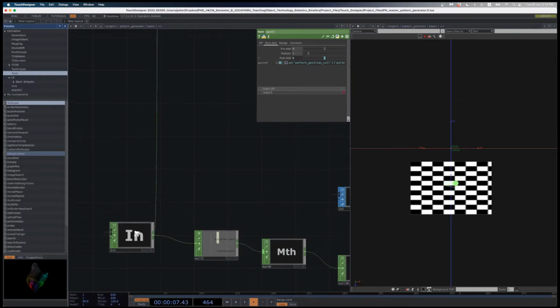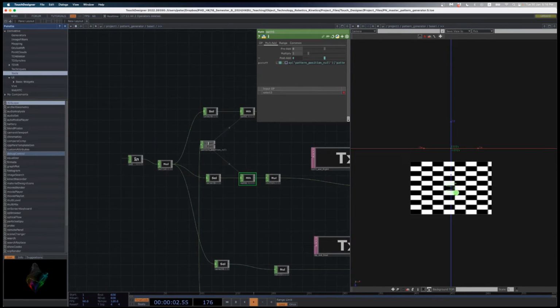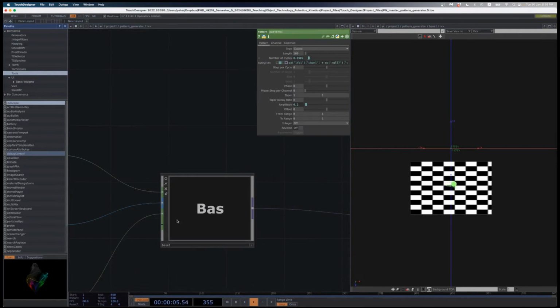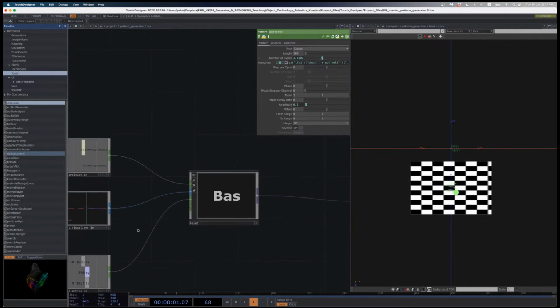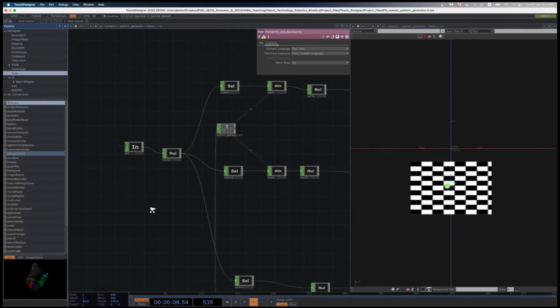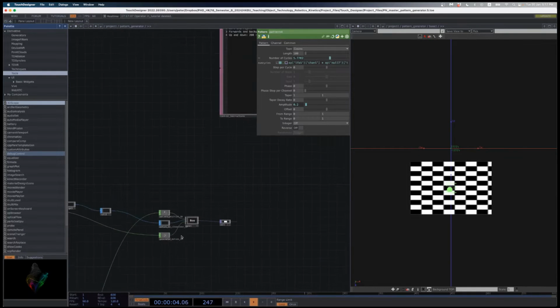And that's what these In things are. There's a bunch of them. When you make a container, if you want to access something in your container, you can just put in a new In of various different types. If I call this In, like, in underscore tutorial, then if we go back to our base, there'll be this new input slot called in tutorial. So that means if we want to send a piece of data into this section, we've now got a little slot to connect it in. So it's a really nice way to keep your file organized and make sure that changes you make in one level flow back down to the next.